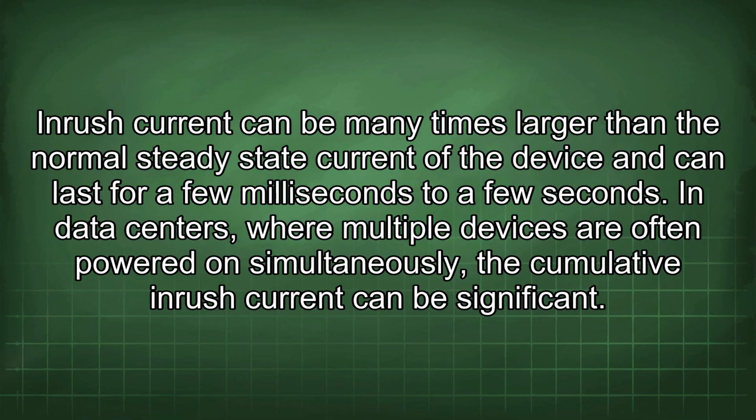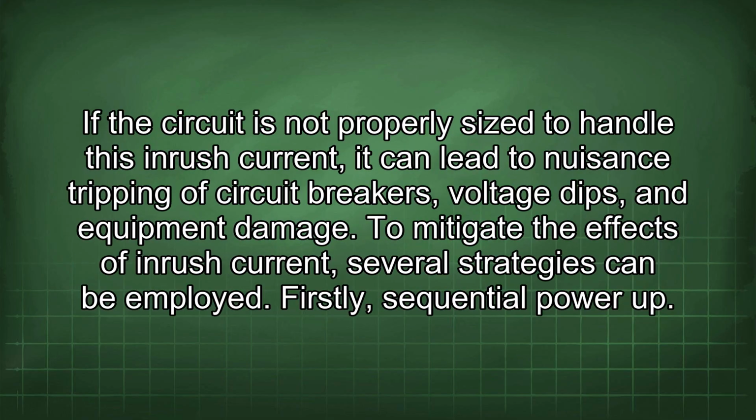In data centers, where multiple devices are often powered on simultaneously, the cumulative inrush current can be significant. If the circuit is not properly sized to handle this inrush current, it can lead to nuisance tripping of circuit breakers, voltage dips, and equipment damage. To mitigate the effects of inrush current, several strategies can be employed.